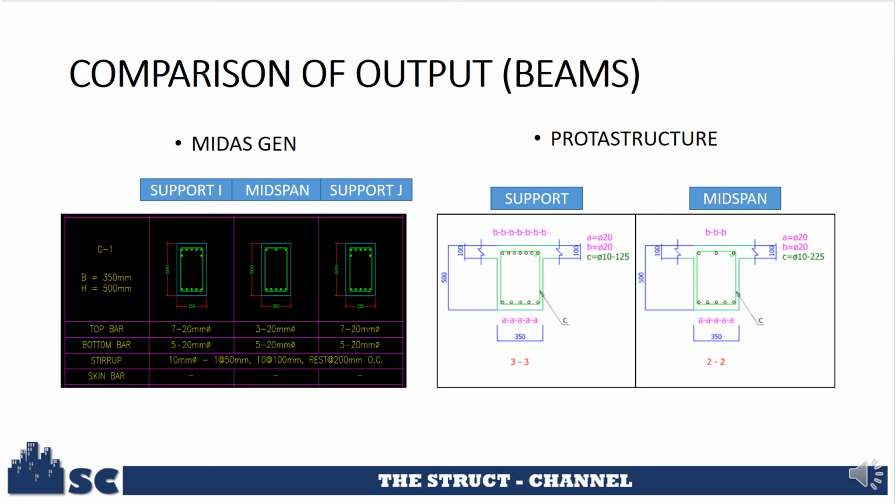Now, I just would like to warn that the Prota bar cutting list is only for the purpose of doing a good estimate of the kilogram, because the software only uses one source length. For example, if you input the source length to be 6 meters, it will only use a 6 meter length of rebar.